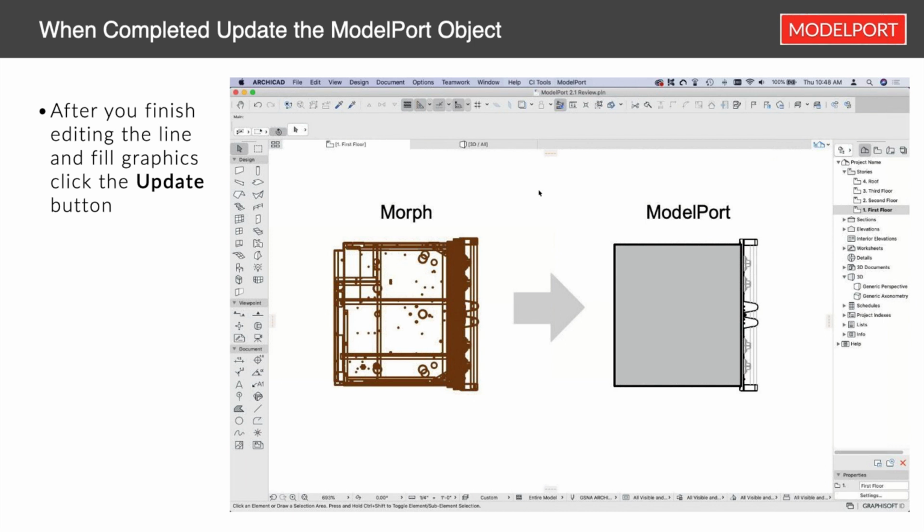In terms of BIM, we're usually not getting up that close, so it's okay to decimate many of those curves. As long as you're far away, you're not going to see it, right? Now, with that said, a lot of flat surfaces we don't want to have triangulated, because if we had those flat surfaces selected, it would then try to also decimate or affect those polygon reductions of those flat panels, which means that that flat panel might turn into 2 or 3 or 4 polygons. And that's something we don't want to have happen.